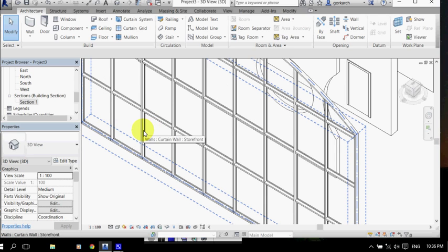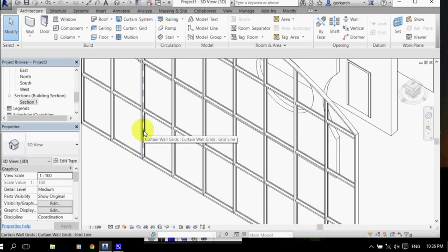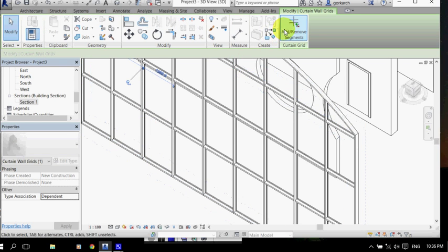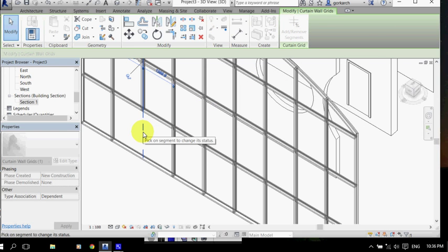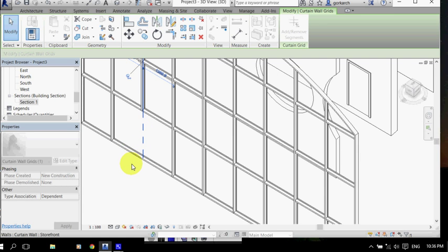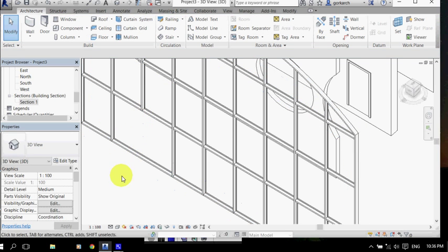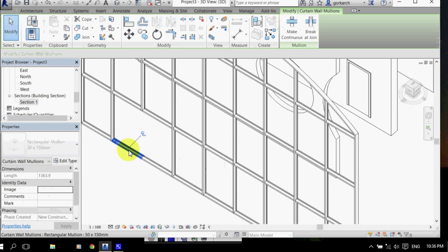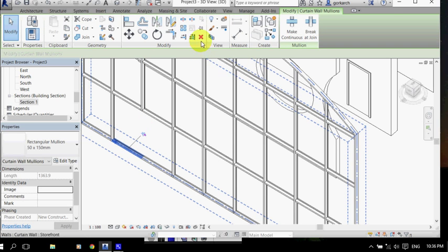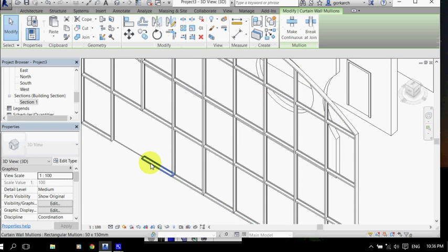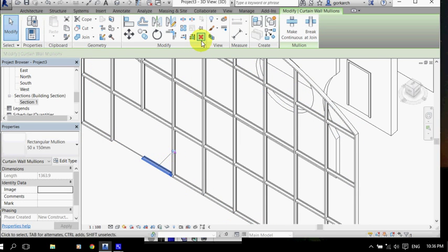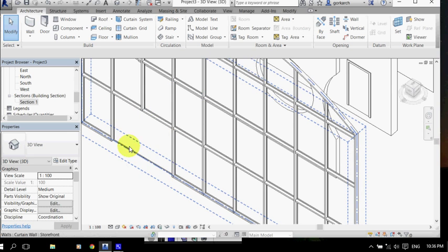Select the grid line. So I'm using tab key. Here's my curtain wall grid. Left click, add remove, left click in the same location. This removes portion of the grid. Escape, escape. No grid, no mullion. I want you to take bottom mullion, unpin it, delete, unpin it, delete. So we're not getting threshold here. It's a dangerous thing, thresholds on exit doors. Now you have open glazing panel.